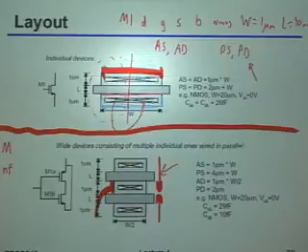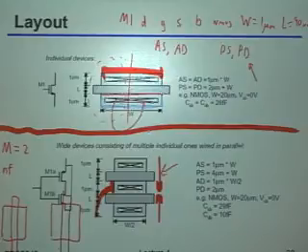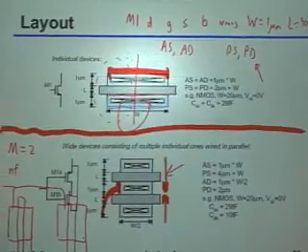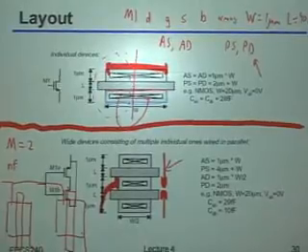Okay, great. So you actually said what it really should be defined as, which is indeed in SPICE, if you say M equals 2 as an example, what it will literally do is take whatever you specified for the original transistor, take another complete copy of that transistor, and tie the two of them in parallel. In other words, all of the terminals will just be tied in parallel with each other. In SPICE, at least, that's the only correct definition for M.